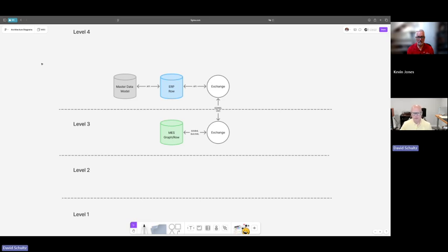So when we get into level 3, again, this is going to be your manufacturing execution system. Within the ISA 95 standard, there are 12 functionalities that exist. Most people are familiar with MES through what's known as the Core 4, and that's, I think, because MES has largely been sold and marketed through some sort of functionality, whether it's OEE, downtime, or material genealogy, track and trace, whether that's statistical process control. Those are the types of functions that you're going to find in an MES.